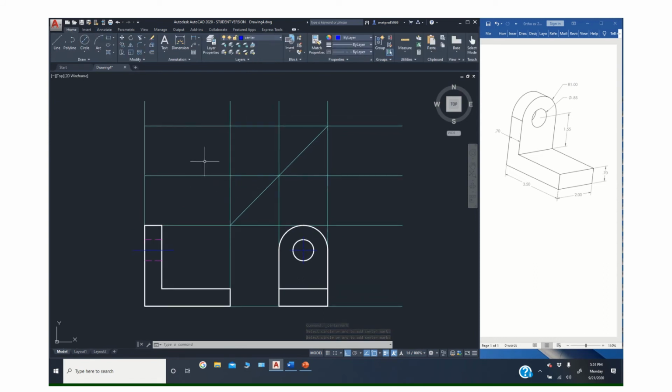So top view, I'm looking down on it, I would definitely see this big rectangle here. Oops, I should put another projection line on there. Right, so that's that surface there. I'm looking straight down on it. Now, again, when I'm looking at this, it's curved, but you can't tell. All you're going to really see is the side. So this side and the back side, this is going to look like a rectangle from this point of view.